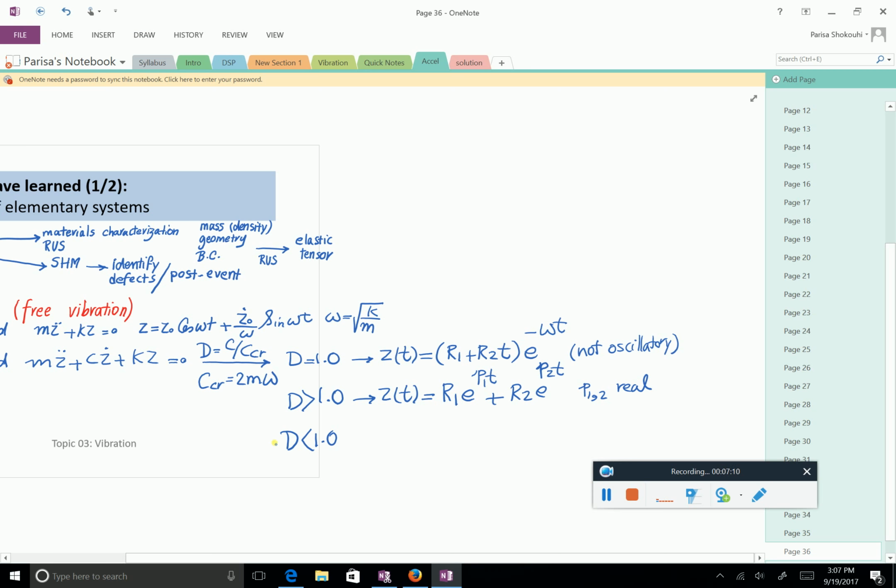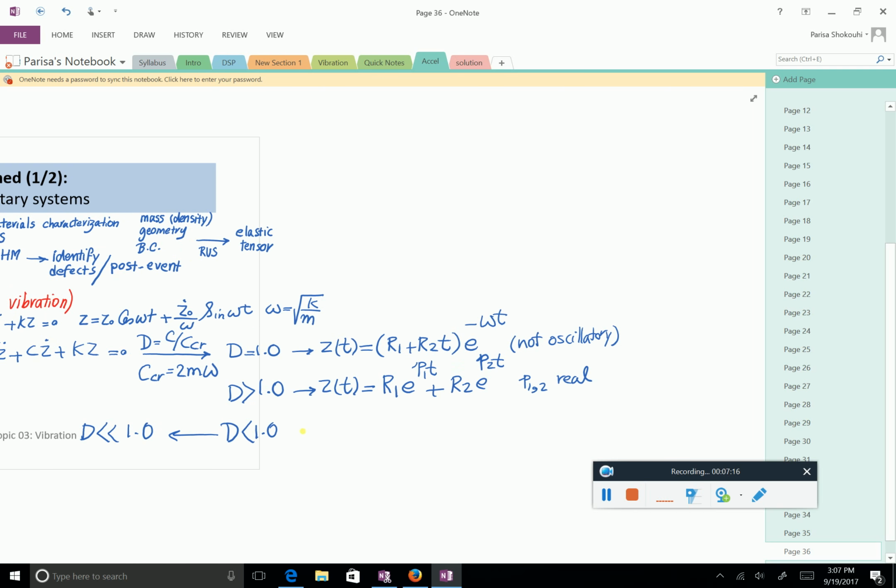These are important, but not as important as the last case, which is underdamped. Typically we saw that ζ is much smaller than 1. In that case, the response was sinusoids modulated by an exponential. You saw it today. Just remember the curves which were ringing down.